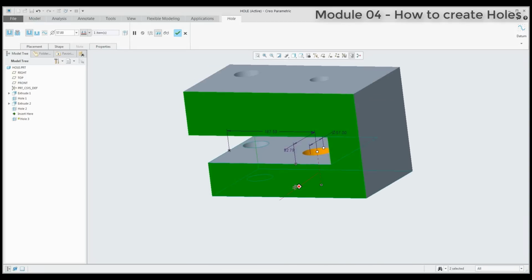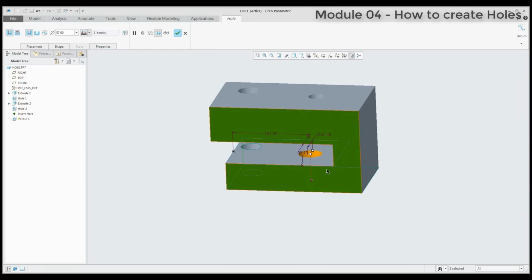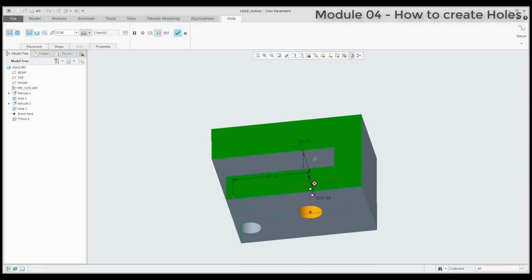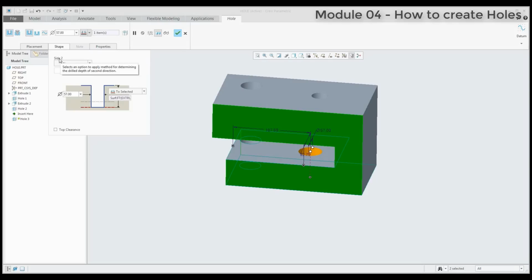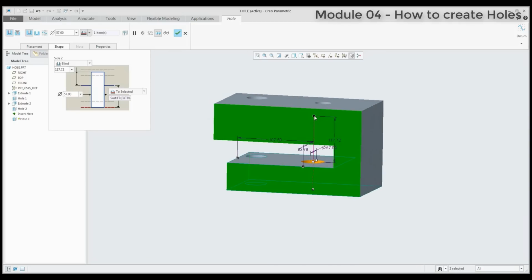Okay. So right now you specify that you would like to create a hole from that surface at the end. The question is that you would like to go to the opposite side. So you can see here in the shape is side 2, and you can choose different kinds of depth. For example, set the number or 2 next, through all, and so on. Yeah? So on the second side, I like to go with dimensions, and my dimension will be, for example, 90 millimeters. Yeah.